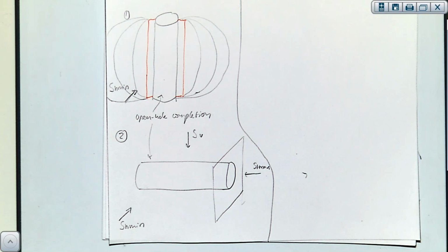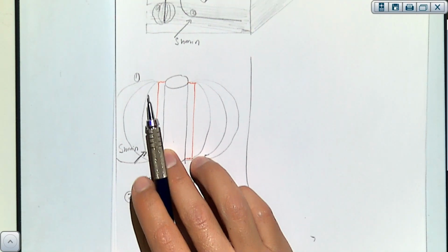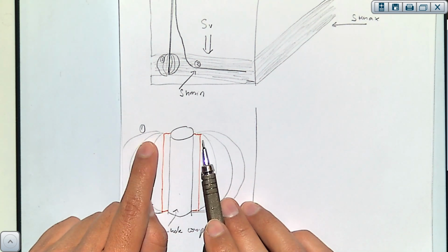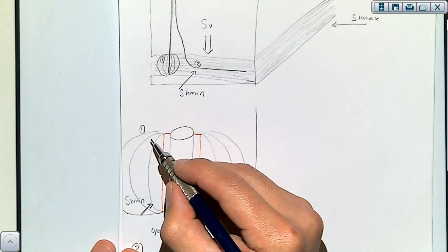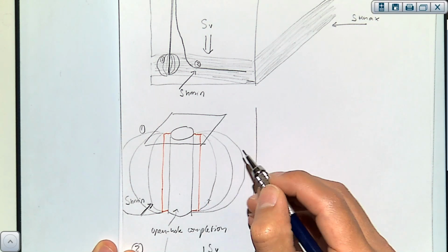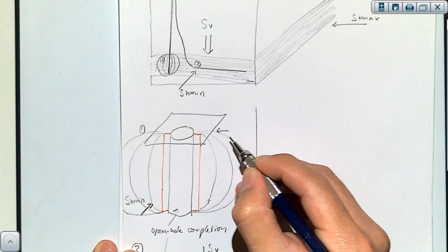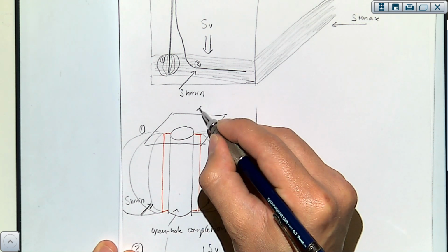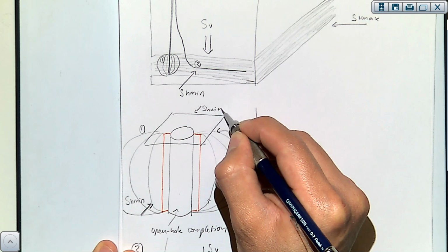Well, but you're answering the second part. But the first part has to do with the distribution of stresses around a wellbore. So in this case, for example, we have these tensile fractures in east-west because if I do the same thing as I did before, notice that this is SH max and this one is SH min.